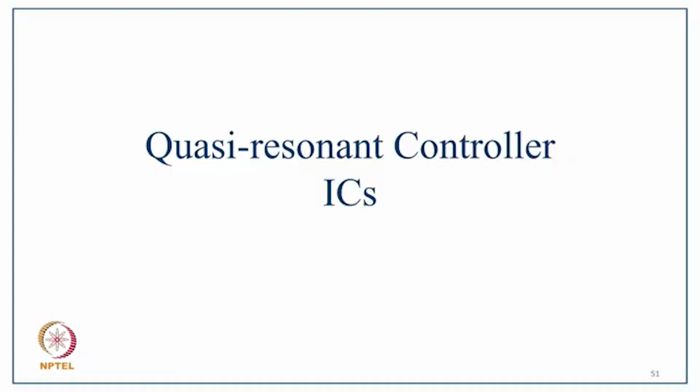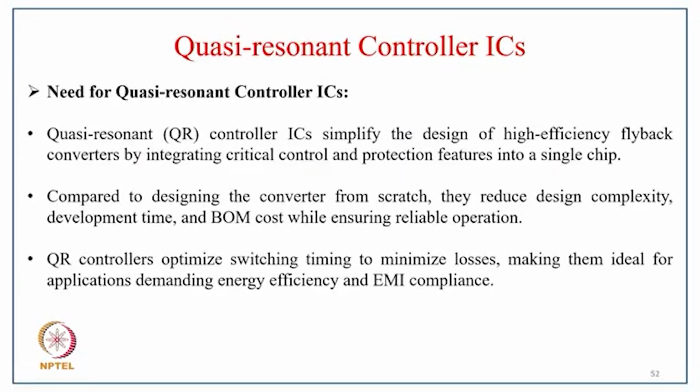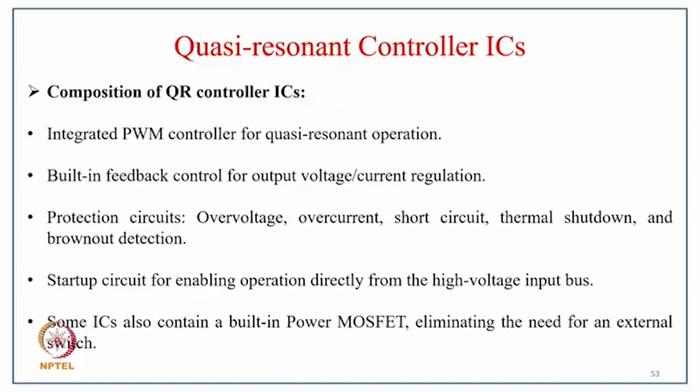And coming to the quasi-resonant controller IC, the need for a quasi-resonant controller IC. The quasi-resonant controller IC simplifies the design of a high-frequency flyback converter by integrating critical control and protection features into a single chip. Compared to designing the converter from scratch, they reduce the design complexity, development time, and BOM cost while ensuring reliable operation. And the QR controller, the quasi-resonant controller, optimizes the switching time to minimize losses, making it ideal for applications demanding energy efficiency and EMI compliance.